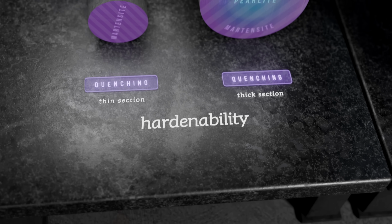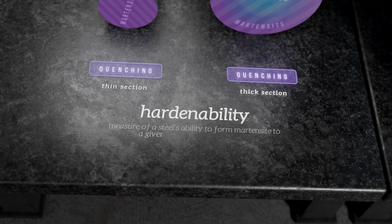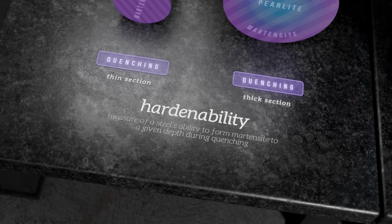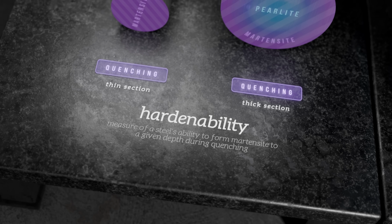Hardenability is a parameter used to quantify a steel's ability to form martensite to a given depth during quenching. A steel with good hardenability will be able to form martensite more easily at slower cooling rates, and produce martensite all the way through thick sections.